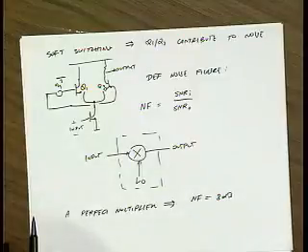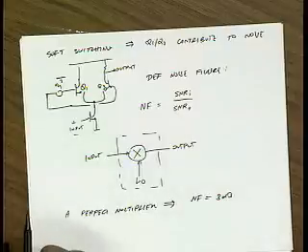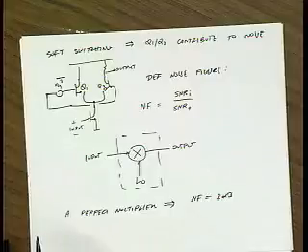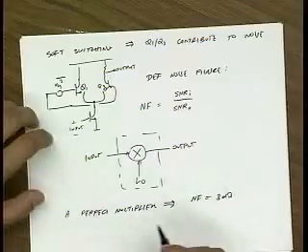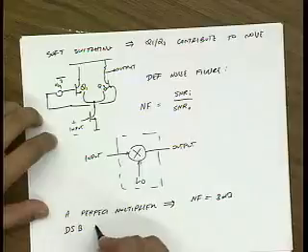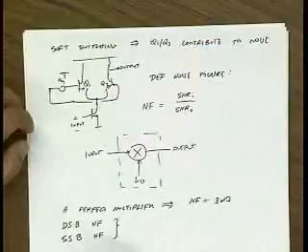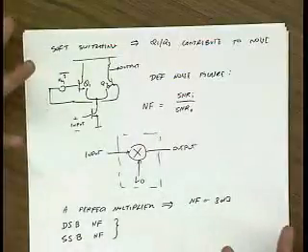On the other hand, someone looked at this and said that's not fair, that means a perfect mixer already has a disadvantage of 3 dB. What if we assume that there's a filter and that the filter actually rejects the image and the image noise? Then you would say the noise figure of an ideal mixer is 0 dB. There's also a complication because you have to take into account if there's modulation in the image band. So there's a double sideband noise figure and a single sideband noise figure. Okay? Double sideband noise figure assumes that you have actual energy in both sidebands.